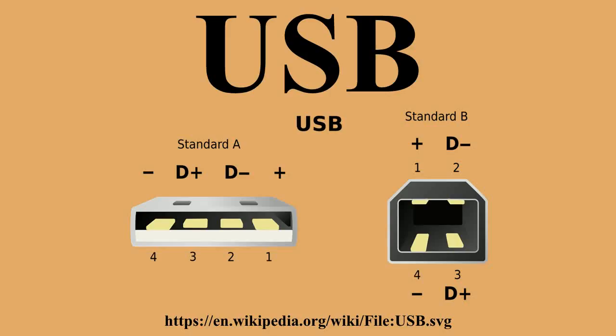A stream pipe is a unidirectional pipe connected to a unidirectional endpoint that transfers data using an isochronous, interrupt, or bulk transfer. Isochronous transfers at some guaranteed data rate but with possible data loss. Interrupt transfers are for devices that need guaranteed quick responses. Bulk transfers are large sporadic transfers using all remaining available bandwidth, but with no guarantees on bandwidth.